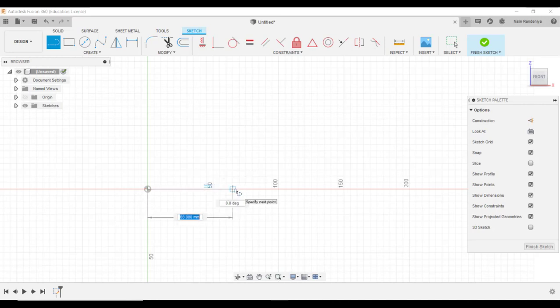Look at where the horizontal axis is, the number 50. You can see there's another symbol, the light blue one. That is the automatically detected constraint. What is that constraint? Horizontal constraint. It just snapped to this, snap in the sense just like a magnet. When I move the mouse pointer down, it gets attached to that horizontal axis for a second until I move the mouse pointer further down. So the horizontal constraint is automatically detected. When I click anywhere, that constraint is already placed.